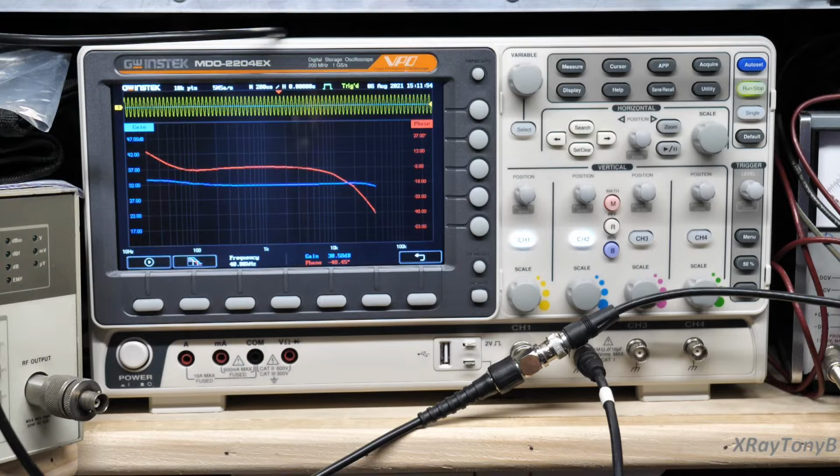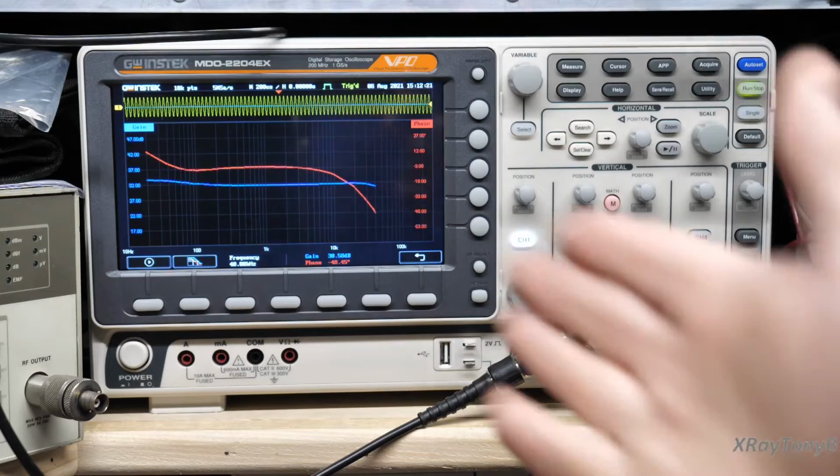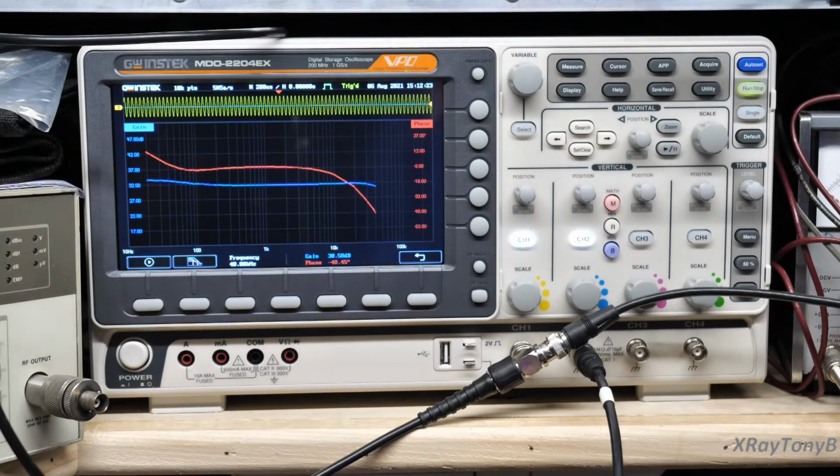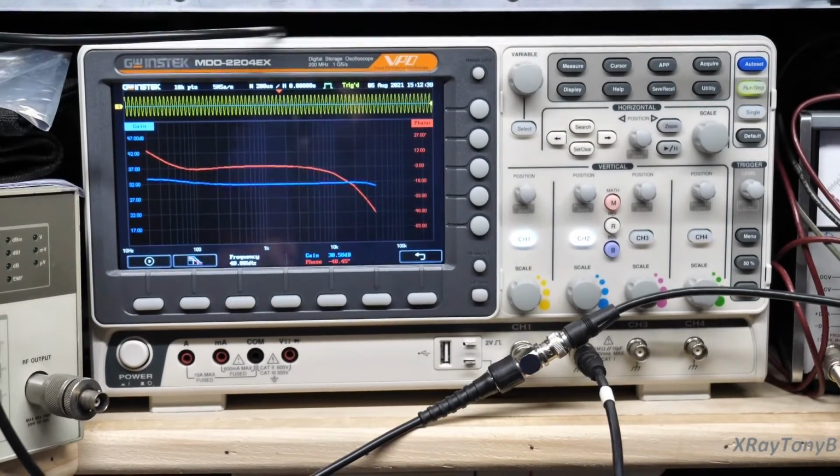In other words, the purpose of a loudness control is to boost the low frequencies at low volumes, because your ear can't hear the bass as well at low volume. It's just an anomaly of the human ear. So that's designed to give a certain dB of gain at certain volume levels to offset the hearing loss of your ear at low frequencies, at low volumes. Pretty cool. And this gives you a graphic representation of it.